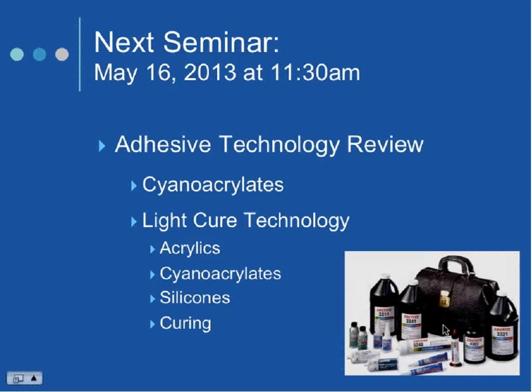But it is critical to store products properly. I can't tell you how many places I go into where somebody thinks they're supposed to store a light-cure acrylic under refrigeration, and that's not recommended by us. Room temperature. Whereas the cyanoacrylate, we recommend that you store it in a refrigerator until you're ready to use it. Once it comes out onto your floor, it doesn't go back into the refrigerator, because now you run the risk of introducing moisture back into the product, and that is the trigger that makes it cure.